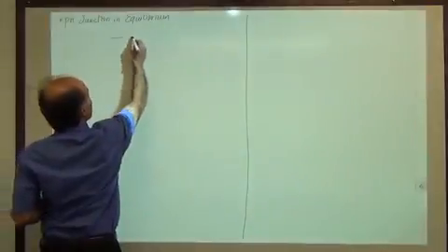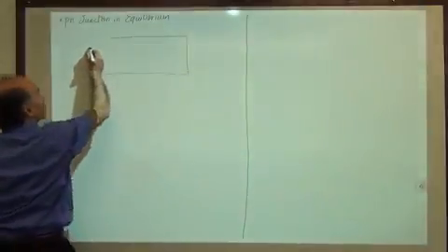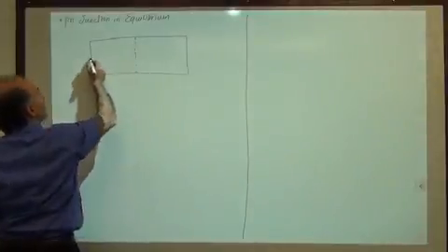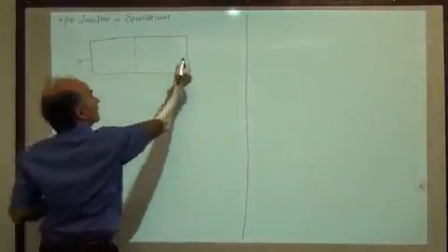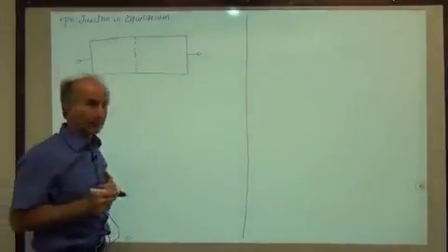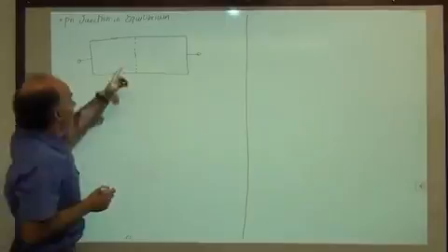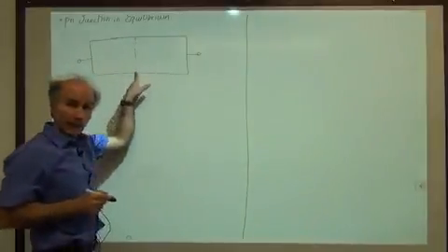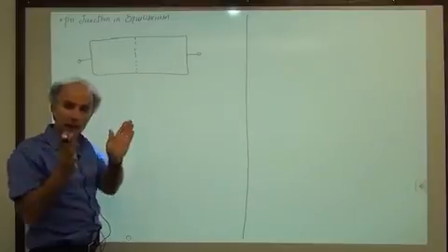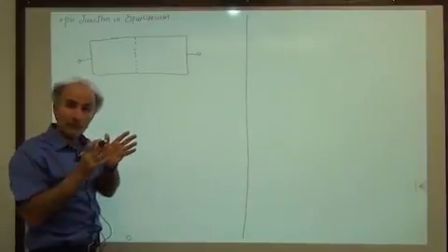So here's our p-n junction. We have the terminals here on the two sides, but they are left open. They're not connected to anything else. Okay, this little line here indicates where the doping level changed from P to N, and we are assuming it is an abrupt change.